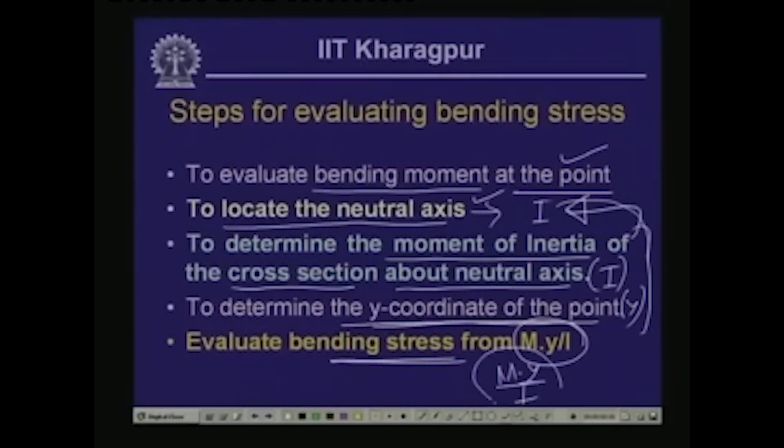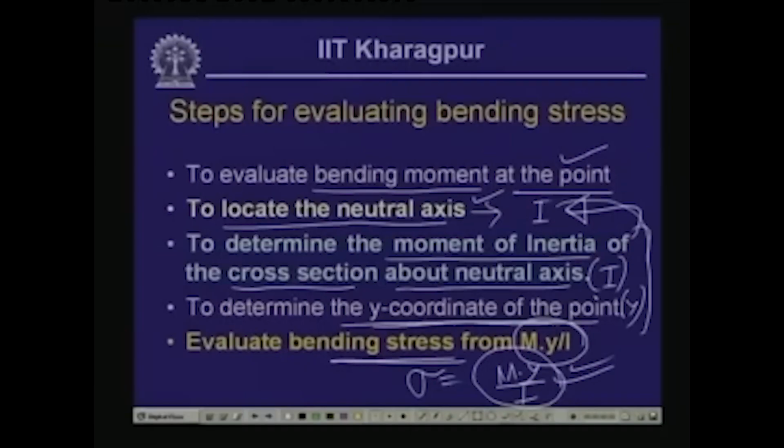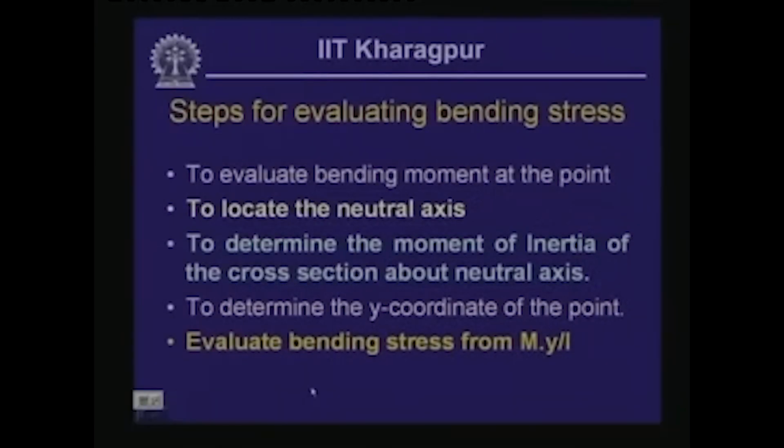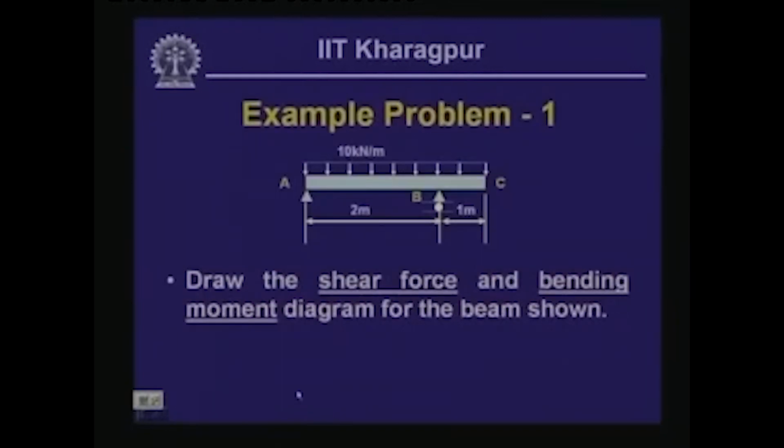Now, here we can take the appropriate sign of the corresponding parameters and the stress can be computed from this, and we can conclude whether it is a compressive stress or tensile stress acting at that particular point. That is how you can visualize how the variation of the bending moment or shear force along the length of the beam helps us evaluate the stress at a point in a beam which is subjected to some kind of loading. Now, let us look into some examples wherein we can apply this technique.